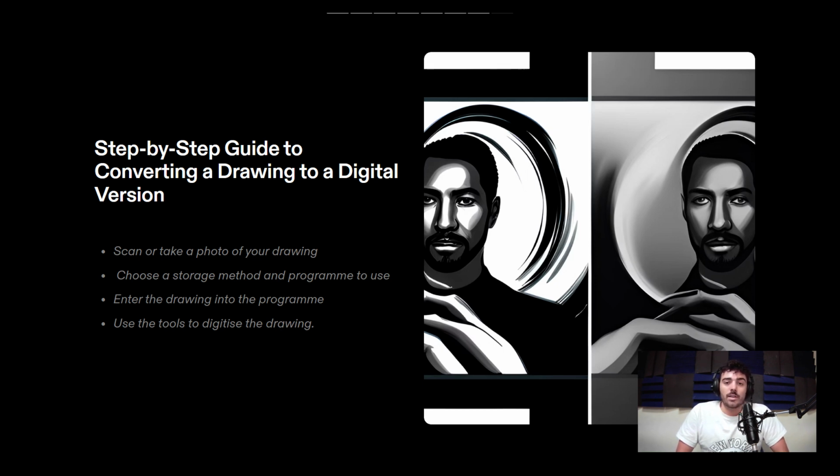If you choose the pencil tool, you can trace over the original drawing using clicks and strokes to create smooth and curved lines. You can adjust the precision and the smoothness of your stroke by modifying the tool settings. If you prefer to use the pen tool, you can create precise control strokes by selecting key points and adjusting curves and lines as needed. This tool may require a little more practice and precision, but it gives you more control over the vectorization of the drawing.